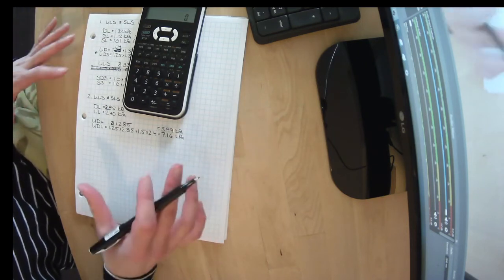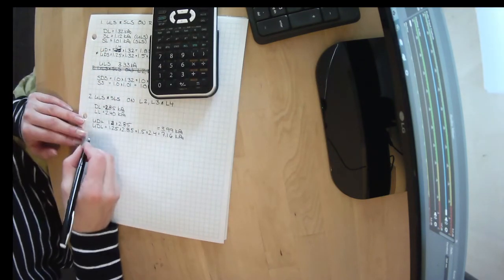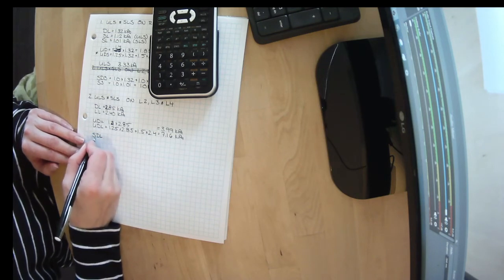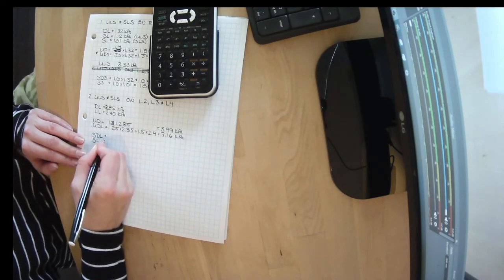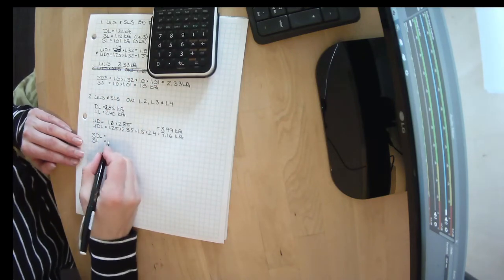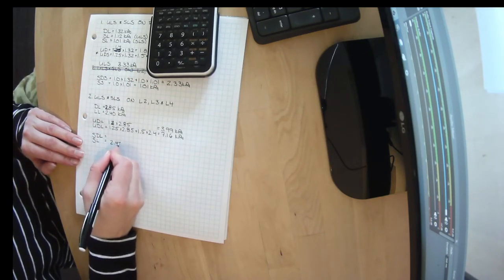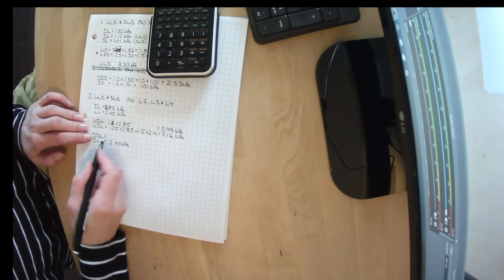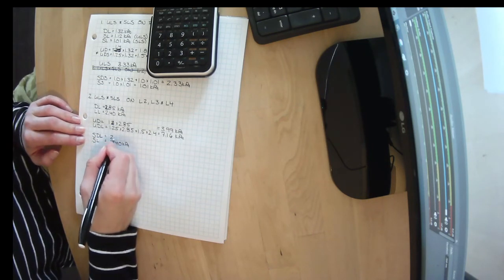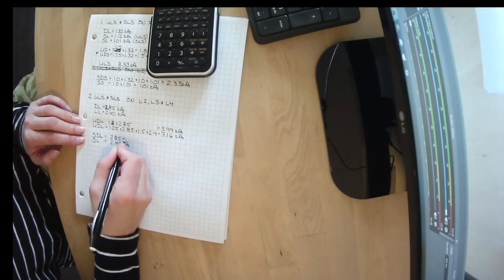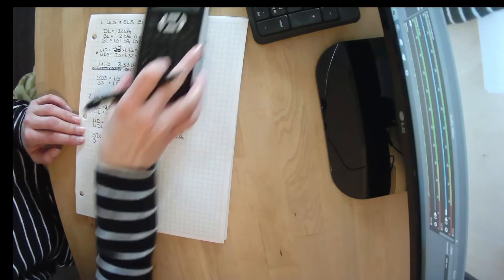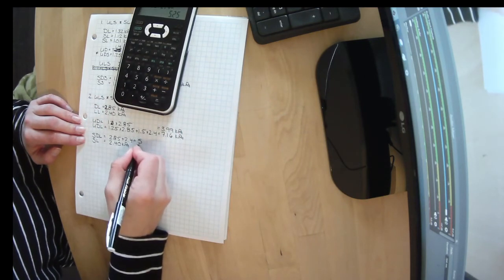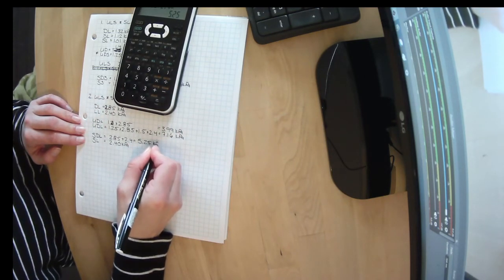That's the weight we would design this floor to. We also have to worry about our serviceability dead and live together, and serviceability live all by itself. Serviceability live all by itself is 2.4 kPa, and serviceability dead plus live is going to be 2.85 plus 2.4, so 2.85 plus 2.4 is 5.25 kPa.